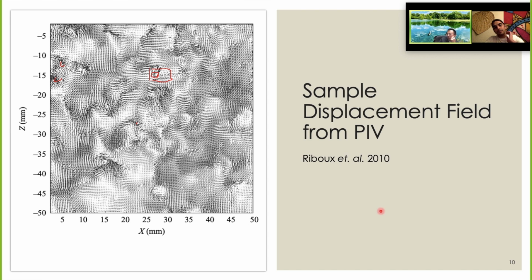And if you have more particles, more bubbles, definitely the light will be scattered everywhere. So you are not going to get a planar image. You are going to get probably the entire tank illuminated. So that will significantly deteriorate the signal-to-noise ratio. And I agree with you for the result part. If your void ratio is close to 40%, as a PIV guy, for myself, I don't trust the result for that part. Okay, it's hard to accept that's a meaningful measurement.